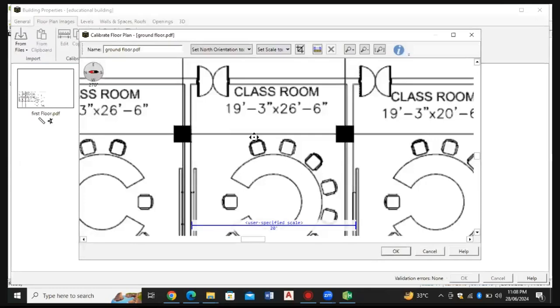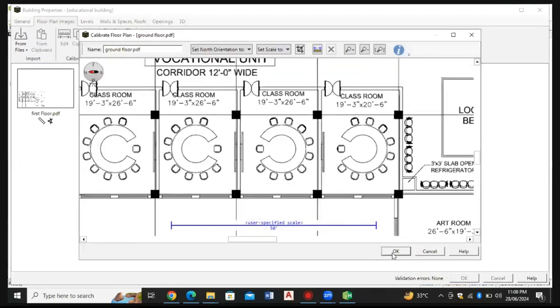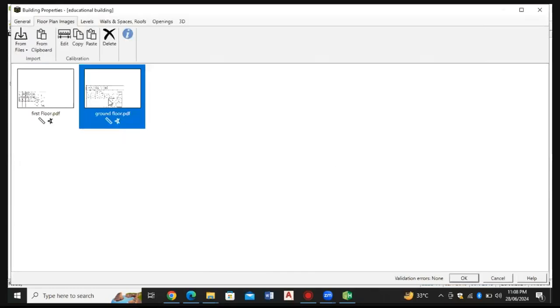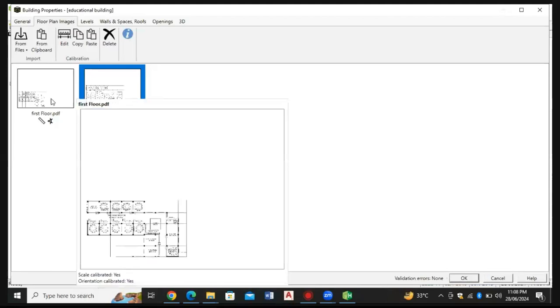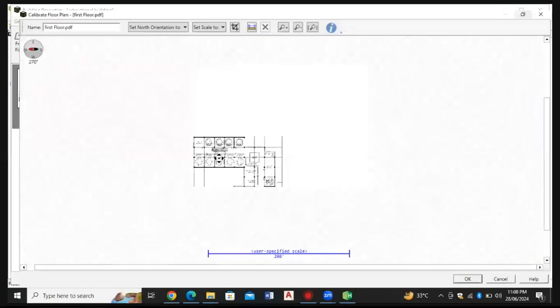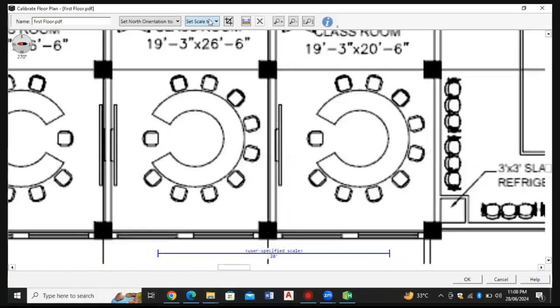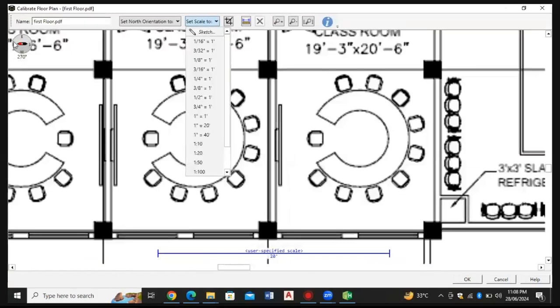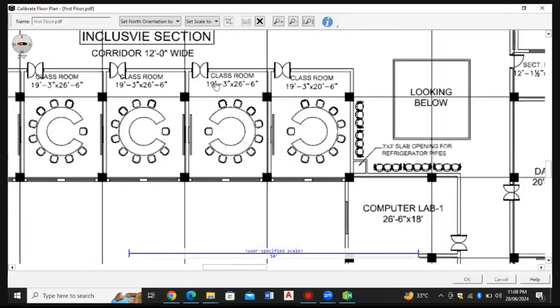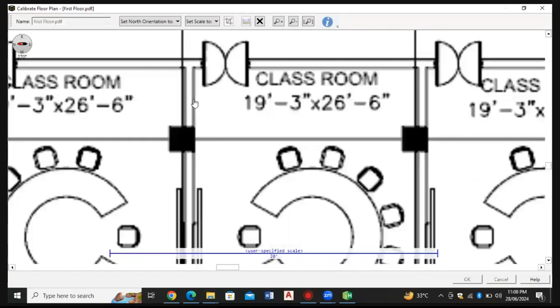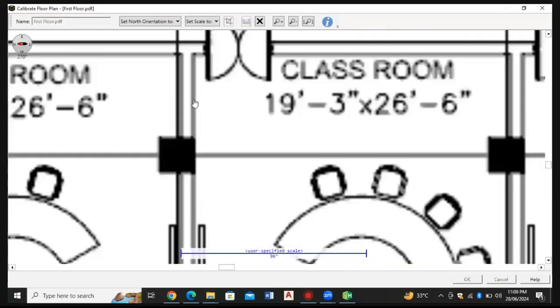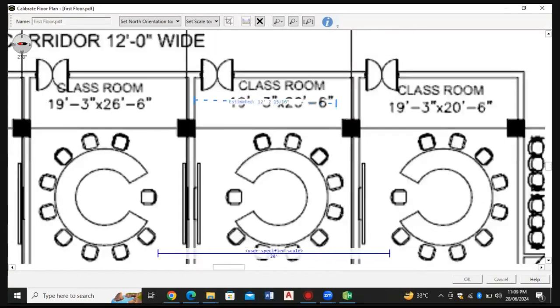Okay, so I think that copy paste will work only if I get a proper scale from AutoCAD to PDF. Sometimes, mostly, it is working. I don't know why it is not working now. But if it is not working, I can do a simple thing: I can give it a scale again. North is selected, but I think because I have not converted at a proper scale, that's why the copy paste is not working. But if you do it at a proper scale from AutoCAD, it will definitely work.